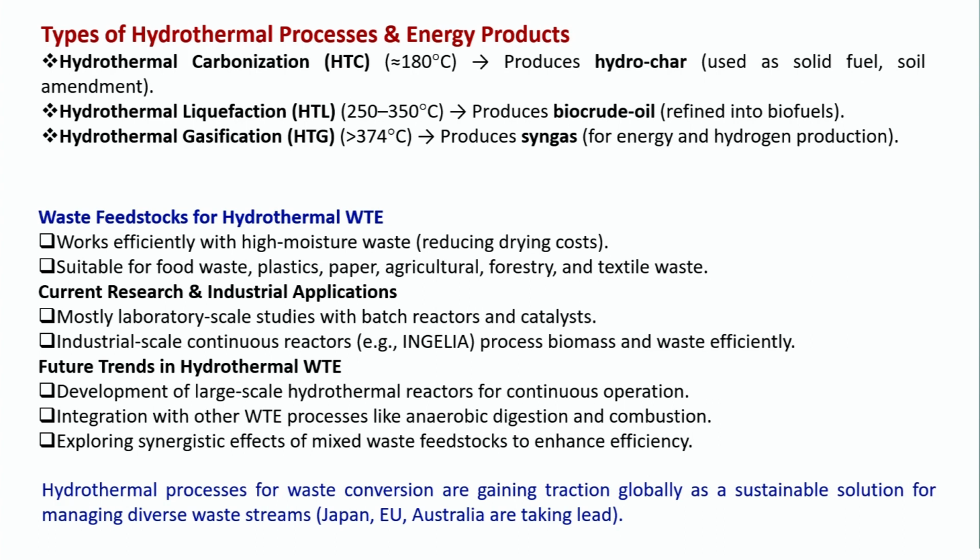These waste feedstocks for hydrothermal processing work efficiently with high-moisture waste, reducing your drying cost. Basically, as I was mentioning, particularly for pyrolysis and gasification, drying is a must. But here, if you have waste containing much moisture, it is not any issue. That means you can always reduce your drying cost. It is suitable for food waste, plastics, paper, agriculture, forestry and textile waste.